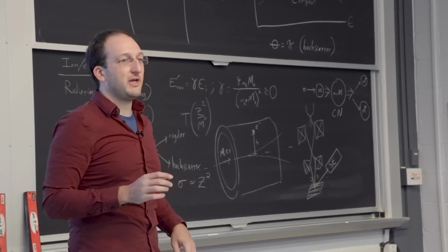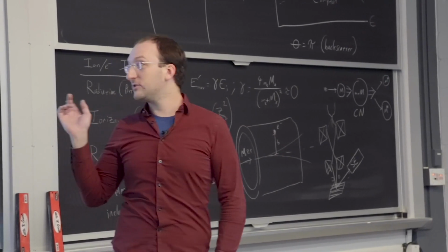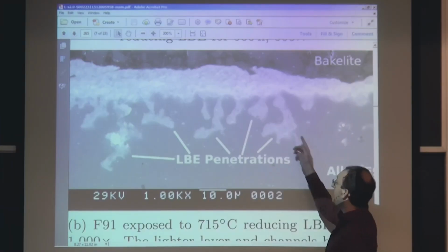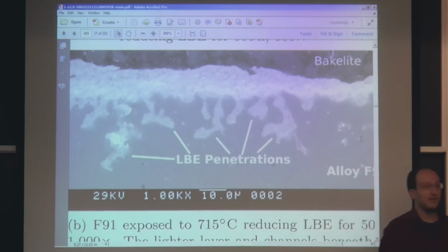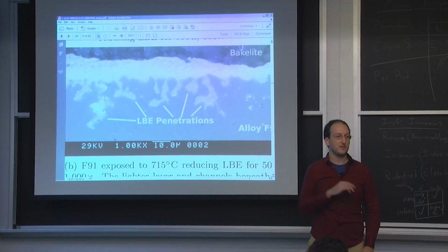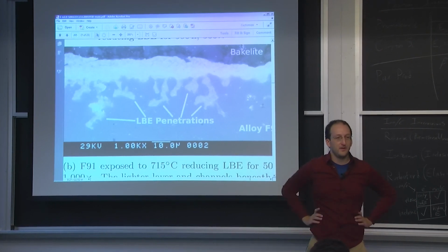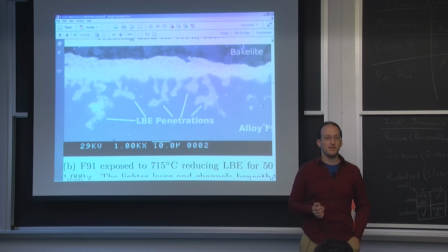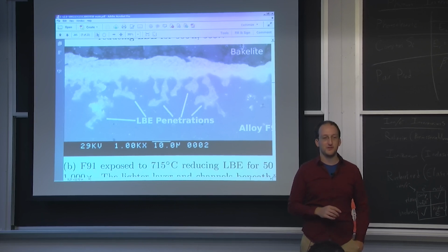So if you want to figure out where the little lead whiskers are penetrating into the stainless steel, since lead has a Z of like 82 and iron has a Z of like 26, it shows up like night and day. Do you have a question, Julia? Okay. Yeah, so this is something we'll actually be able to do. So for the two folks I asked to bring in samples, if you want to bring in something with very different elements in it, we should be able to see it in backscatter contrast very, very clearly.